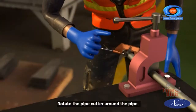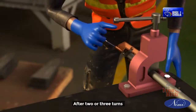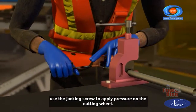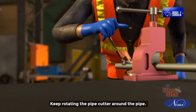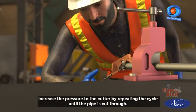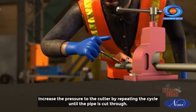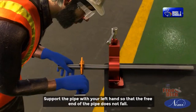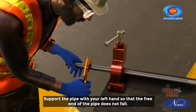Rotate the pipe cutter around the pipe. After 2 or 3 turns, use the jacking screw to apply pressure on the cutting wheel. Keep rotating the pipe cutter around the pipe. Increase the pressure to the cutter by repeating the cycle until the pipe is cut through. Support the pipe with your left hand so that the free end of the pipe does not fall.